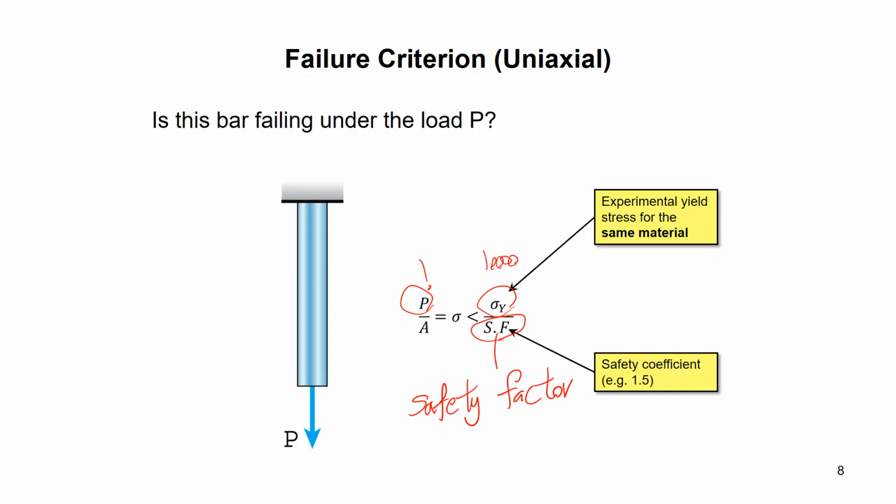Well, does it mean that whatever rope you buy from that manufacturer, the yield strength is 10,000 psi? No. It's just an average that they are reporting out of all their different products. If you take probably 10 of them and test them like that tensile test that I showed you, then you probably see a range of numbers, right?